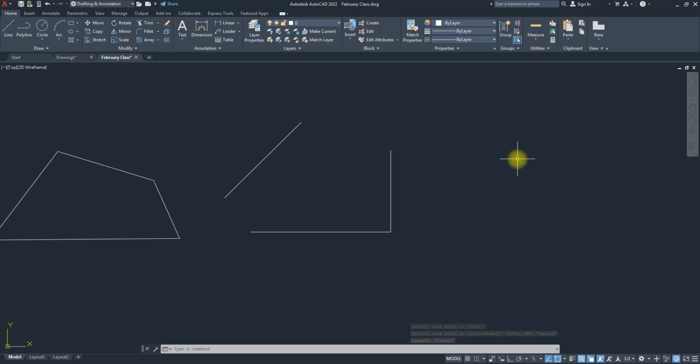We already know three now. On Wednesday we looked at grid F7. Today we've looked at auto mode F8 and dynamic input F12. So you know the function of grid mode. It turns the grid on and off. Dynamic input turns on and off all this construction line stuff. Then your auto mode turns on constraining your line vertical and horizontal.